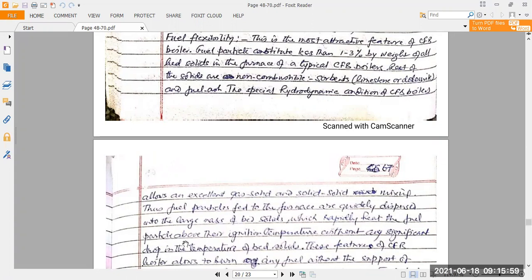The fuel which comes in is comparatively low in temperature, at normal surrounding temperature. So to a certain extent additional heat is required, even in terms of heated air. This time is important because the heat generation will be affected if the fuel bed is not properly heated quickly.